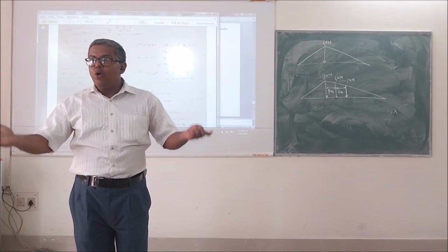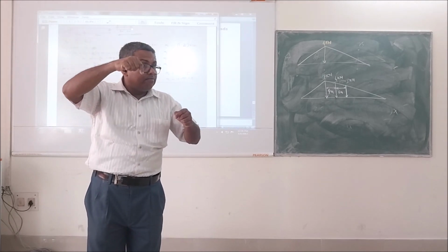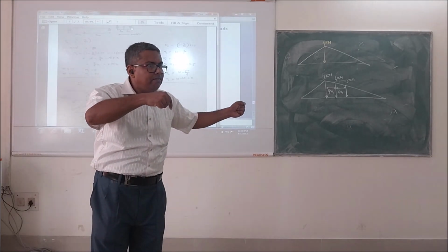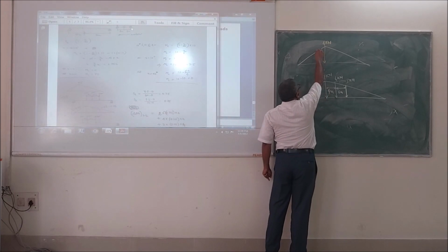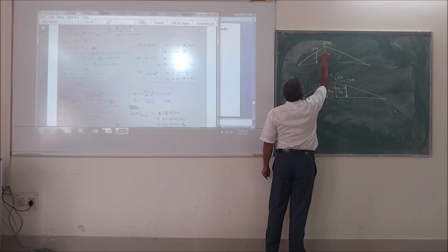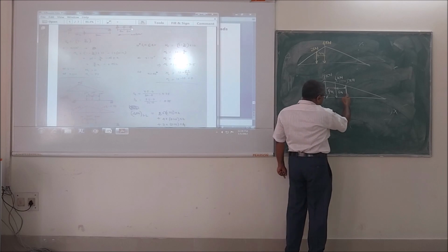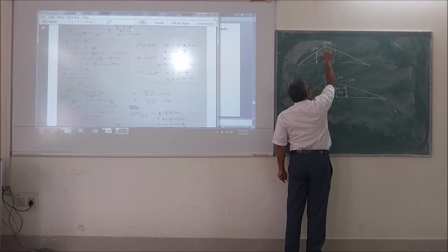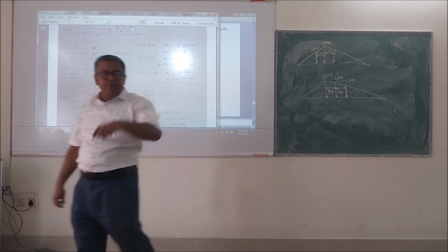Then, we are considering the middle load to move by 4 meter. So if the middle load moves by 4 meter, then the front load will also move by 4 meter, right? So front load is moving by 4 meter. That means this 2 kilonewton load will be coming somewhere over here, right? So here it will be 2 kilonewton. Here the distance will be 4 meter itself, right? However, this 6 kilonewton load, the 3 kilonewton load, will be positioned at 6 meter distance only. The position will not be changing.